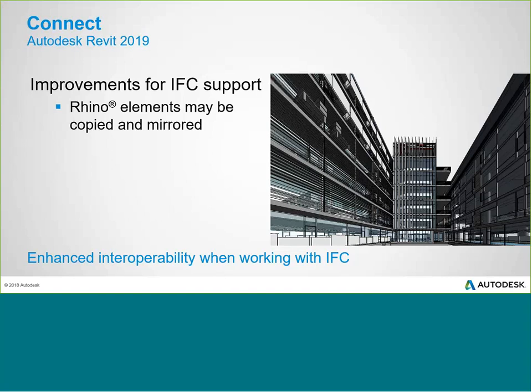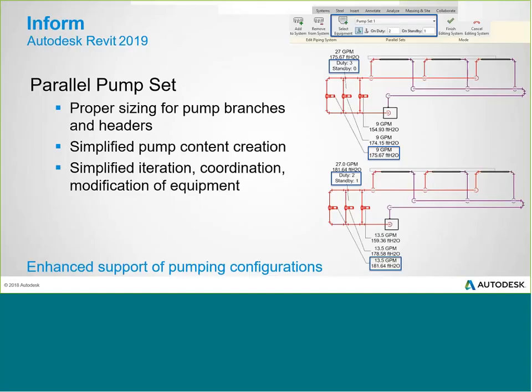And then finally, the last thing that I have for information that we're getting, this is more specific to MEP, and even more specifically than that to plumbing and piping, but we have parallel pump sets, so you can control proper sizing without having to worry about all of those flow rates and the order that things are connected to a system. So in the past, there was kind of a tug and pull between settings and getting stuff to calculate out the right way.